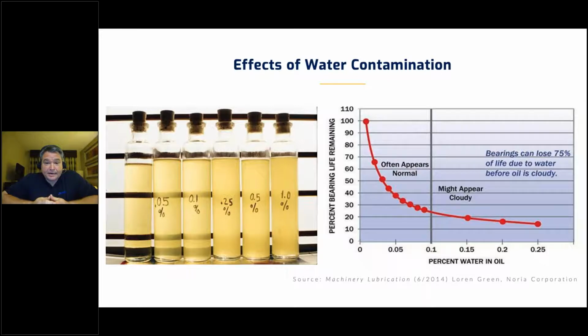So let's look at what lubricant manufacturers say about this. In these studies, SKF determined that 75% of bearing failures in regards to water contamination can happen before the water is visible. It's commonly said that water and oil do not mix.